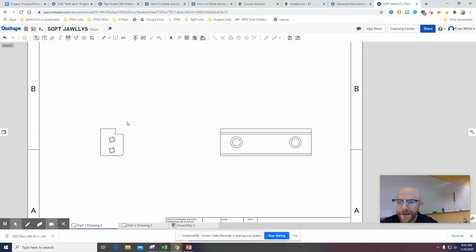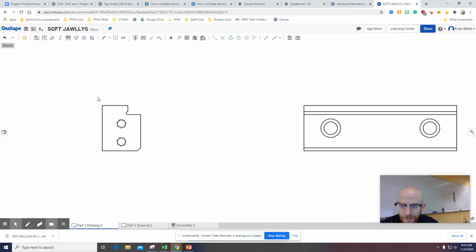So moving back to my dimension tool up here, I will click on 2 lines. So I click the dimension tool, I click on the left side and the right side. I'm not clicking down right now because that's not the dimension I want, but I'm saying dimension from that line to this line, move it above it. Now, if you look at the Canvas drawing, it is quite far above it because we are trying to clear it away from other dimensions.